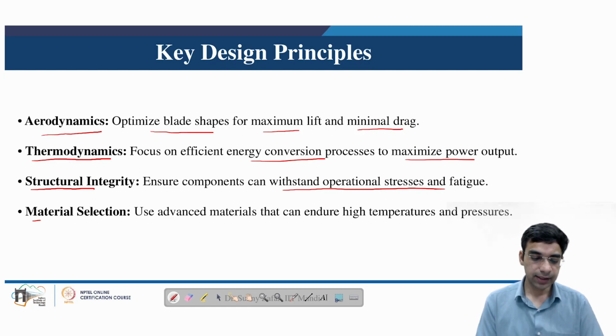And the material selection, as we have just highlighted, in all four types of turbines utilizes advanced materials ranging from nickel based superalloys to high performance advanced structural polymer composites, which can endure the different conditions in which the particular turbine is operating, be it high temperature conditions for a gas turbine or maybe the varying wind conditions in the case of a wind turbine.